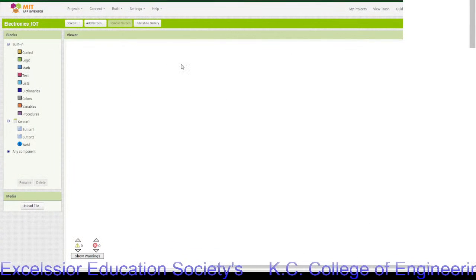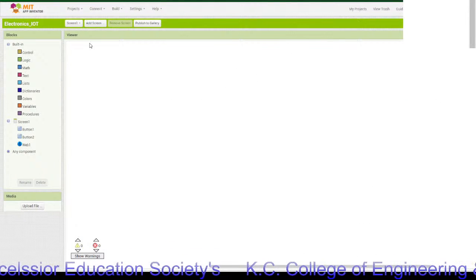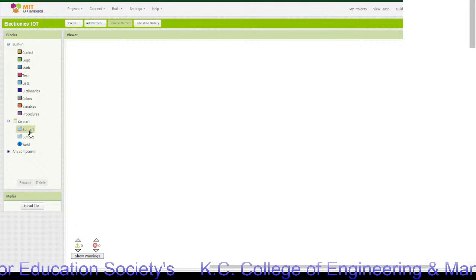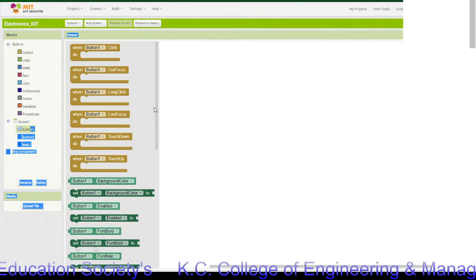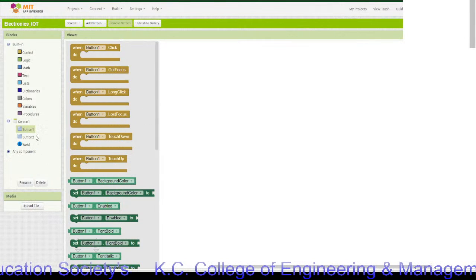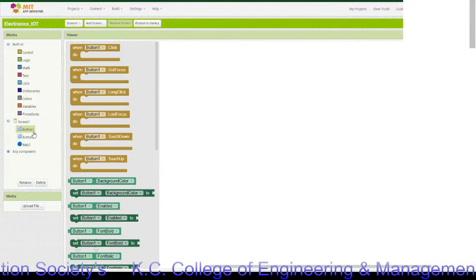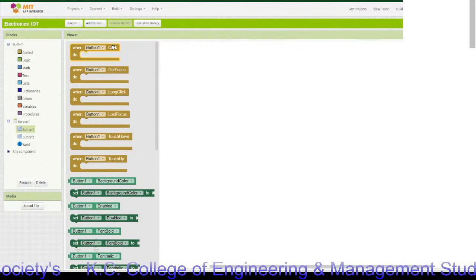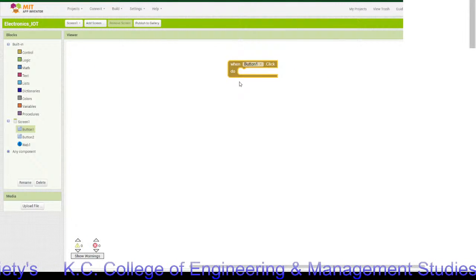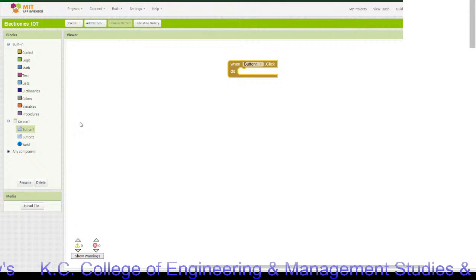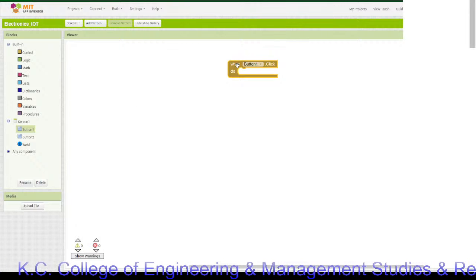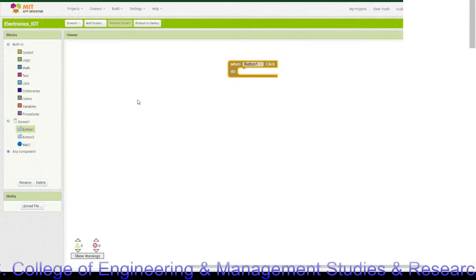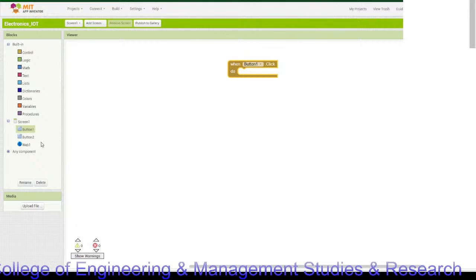Now you will see that blank space. In the viewer, you can add logic over here. For that, our first logic is turning on that LED. So I'll click on button 1. Here you will see lots of options. What I require is, if I click on that button 1, something will happen. Something means we want to hit a URL that has been provided by ThingSpeak Cloud.